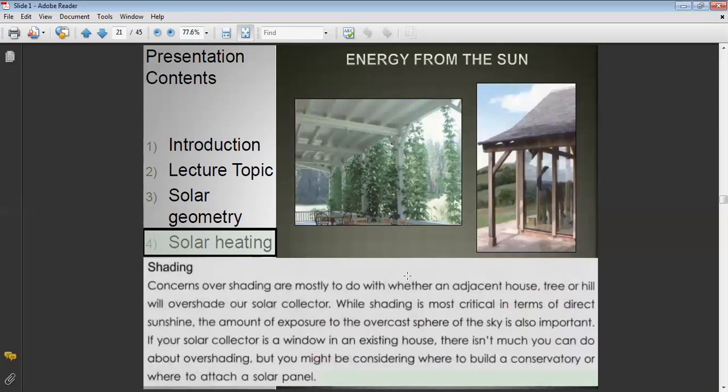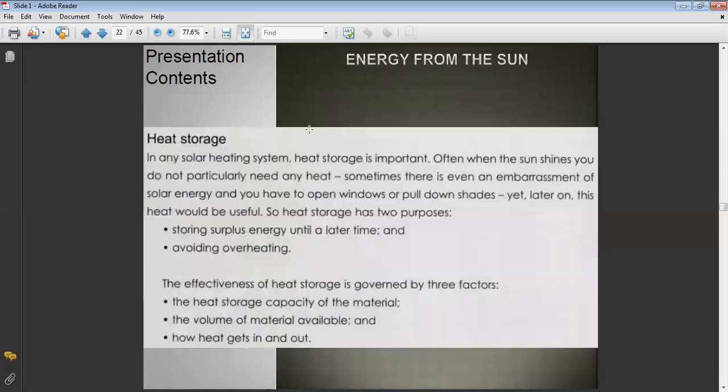So we can use shading devices to obstruct, just like we are having shade over here, and we are having on the right hand side picture, as you can see, we are having shade. This shade above is basically because of a tree or something which can be seen, and the glass surface is going to retain the heat. Over here we have got trellises, so shading devices can be used based on these principles of orientation to ensure how these can be improved.